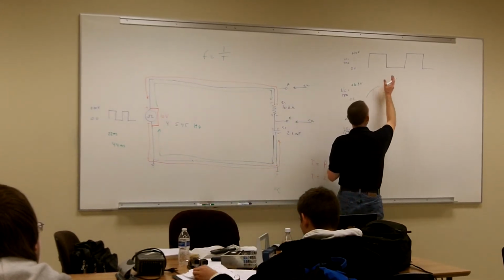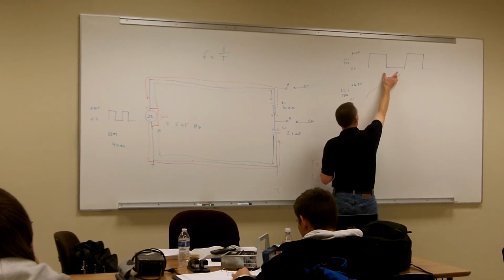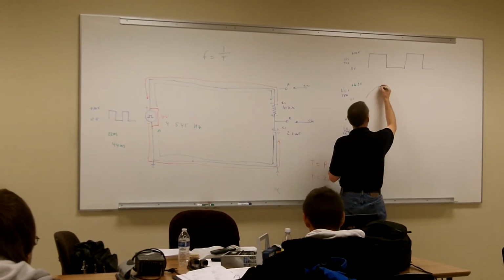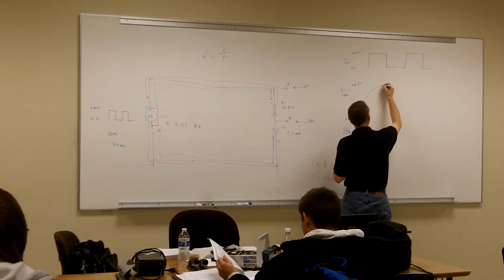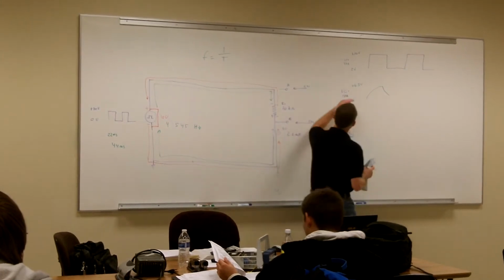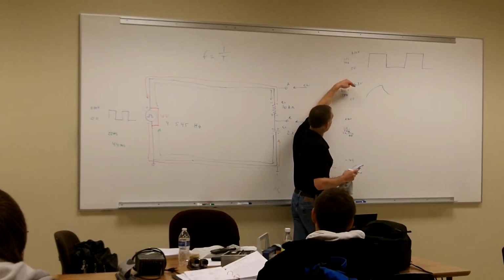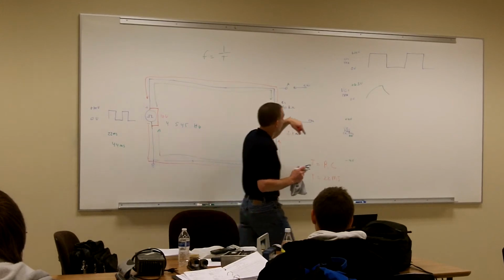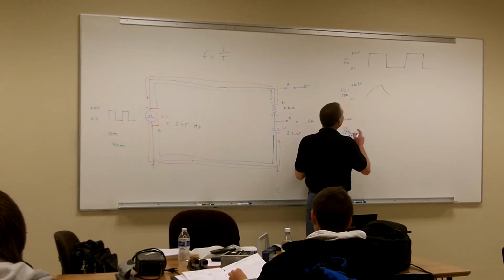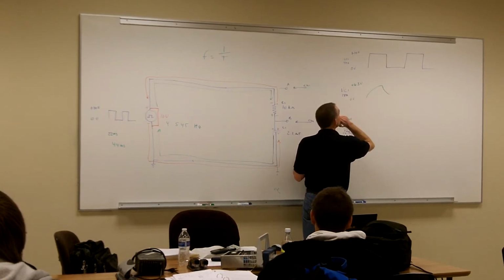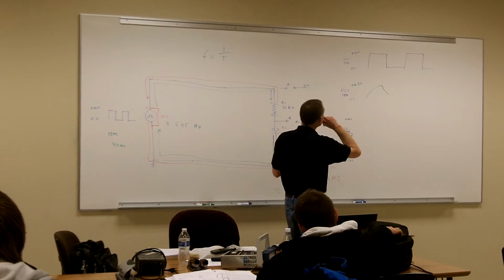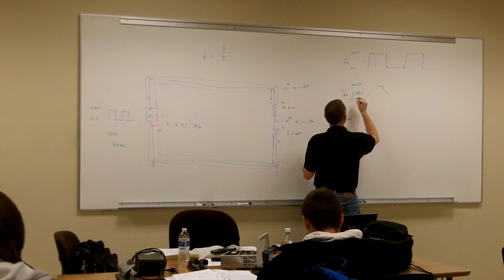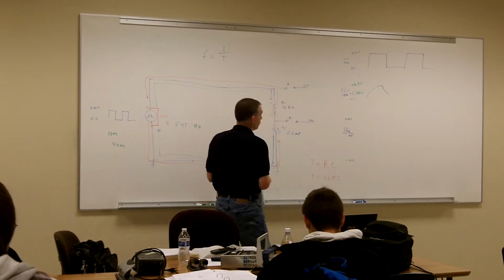And then when the source transitions from high to low, even though it's at 10 volts still, my capacitor only took in that 6.3 volts, and it's going to discharge to 37% of that. So it will be 37% of 6.3, which is 2.331 volts. It's going to discharge down to only 2.331 volts.